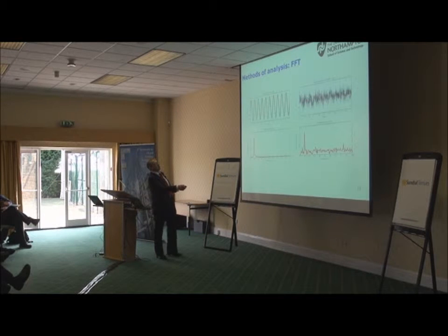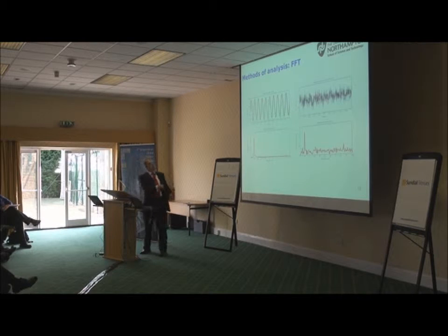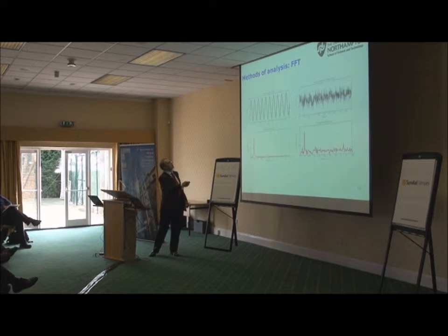When you have a signal of this type, well, we see the amplitude of the vibration, but what is the frequency? We could take these two points, measure the time, and invert it to get the frequency. Here, we need to do FFT, and FFT tells us what is the main component.